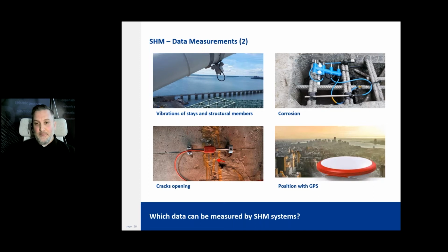On the upper right, we have the ladder corrosion sensor, an interesting sensor because it's the only chemical attribute sensor on the list. It gives indicators for the onset of corrosion and or rate of corrosion. It's embedded, as you can see there, at rebar depth, and it's deliberately positioned at that sort of angle. You can see it's above one set of rebar and below the other.